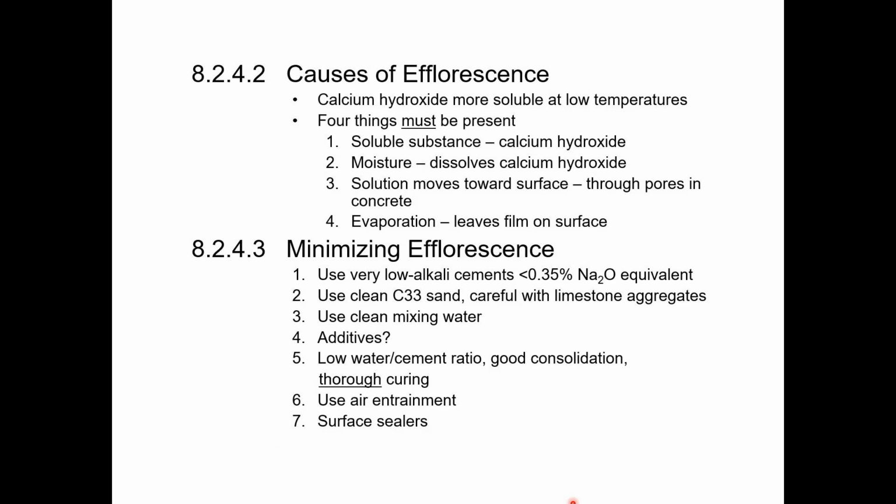I'll say maybe. If the differential camber is just a little bit, maybe it's a quarter inch, or just out of what the project specs say, and you're putting a thicker 2 or 3 inch topping slab on it, obviously, to your point, that's going to cover up any differential displacements in the camber from piece to piece.